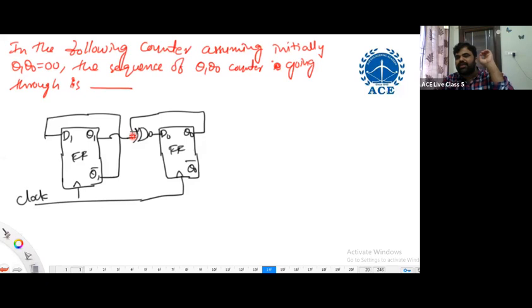While designing a counter, we used the excitation table. While estimating the next state, when we know the present state, the immediate next step is: based on the present state, what inputs are we getting? Once we know the present state and present inputs, we estimate the next state using the characteristics of the flip-flop. Again, the next state is considered the present state, and we proceed until the sequence repeats.